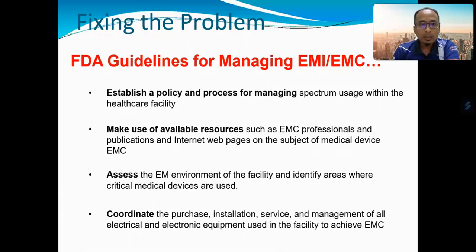All right. So the second guideline given by the FDA is to make use of available resources, such as EMC professionals and publications and internet web pages on the subject of medical device EMC. So what it means is we leverage the knowledge of EMC engineers, clinical engineers, and also resources from FDA, IEC, and also IEEE, in order to make informed decisions about equipment design, selection, placement, and also maintenance.